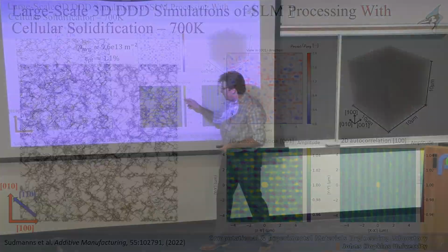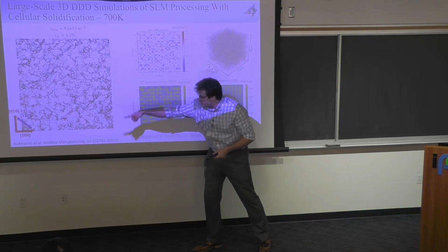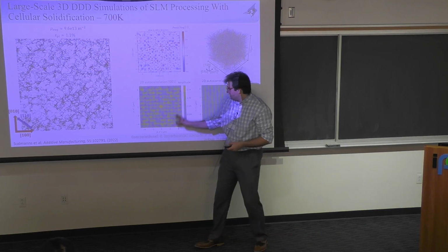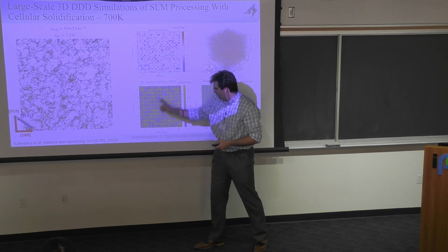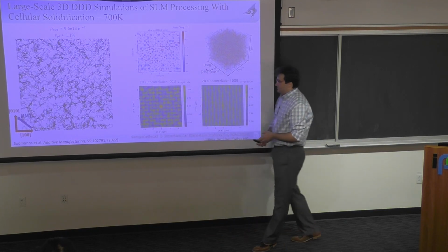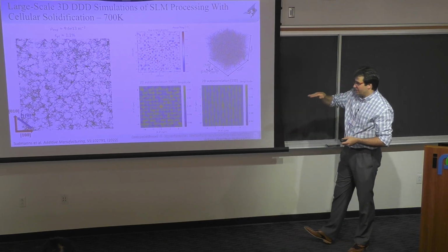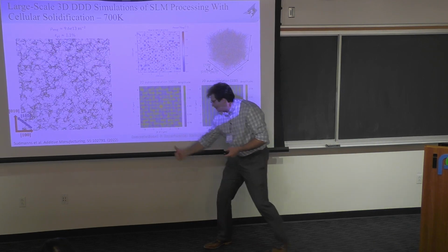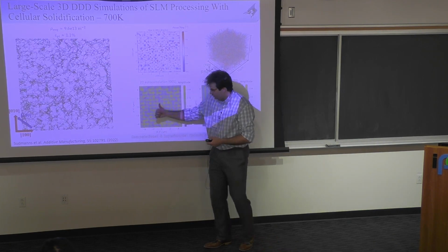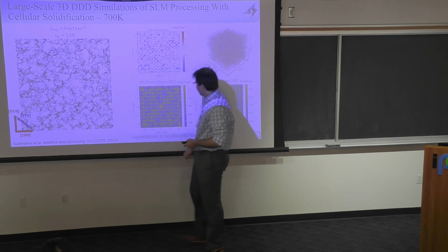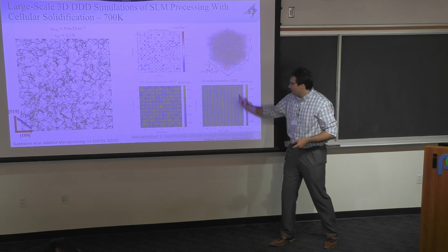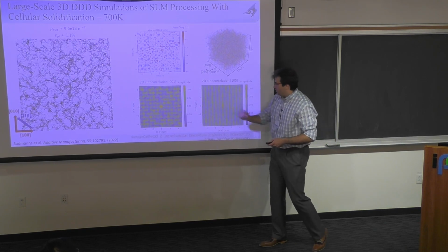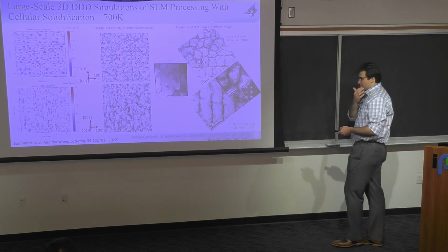And if you do that in this specific orientation, which is a 010 versus a 100, you can clearly see that there is a pattern forming. The yellow represents that pattern. There's a very nice pattern forming along these high dislocation density regions. If you look at it from this point of view, with an orientation this way, and you do the 2-point correlation, you get these types of patterns. They're elongated. There's nothing horizontal. It's all elongated. How does this compare to experiments?